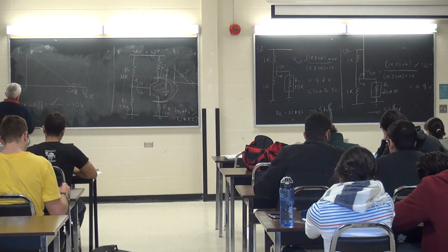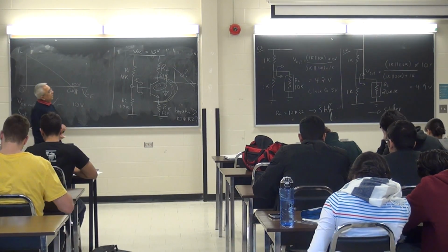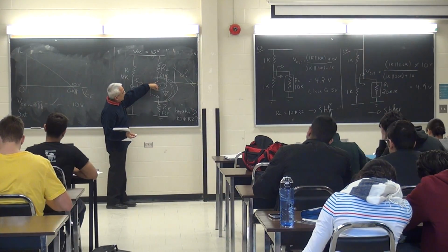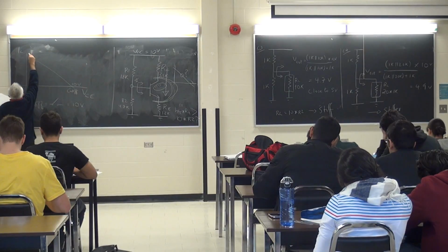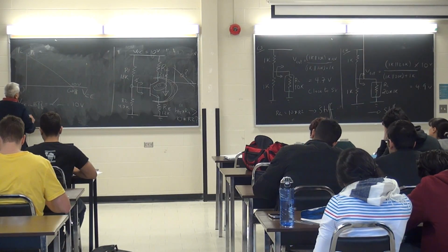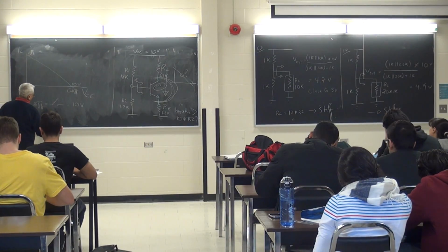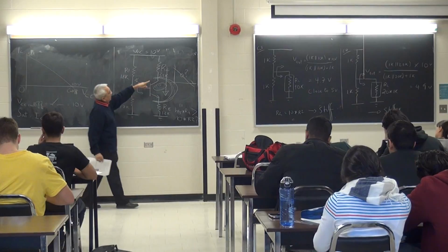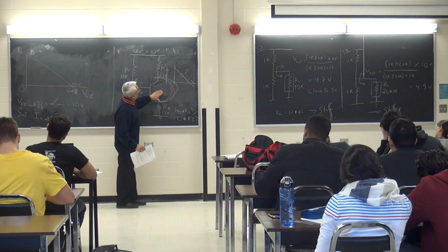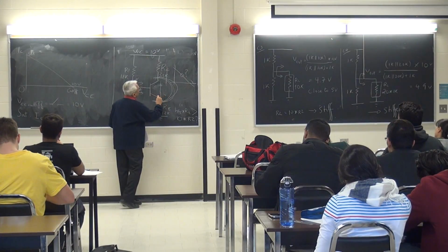Next, saturation. Saturation is when the transistor is fully closed. So that's the other point right here. Let's calculate that, IC sat. Suppose I replace my transistor with a closed switch.